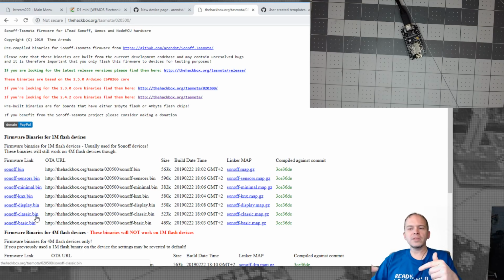And I usually recommend to people to also put a second Wi-Fi address in there without a password, that way you could just remember that SSID, and then you could go make a Wi-Fi with no password, and it would connect up, and you wouldn't have to open that device, which could be bad for some plugs because maybe you had to destroy the plug to open it.